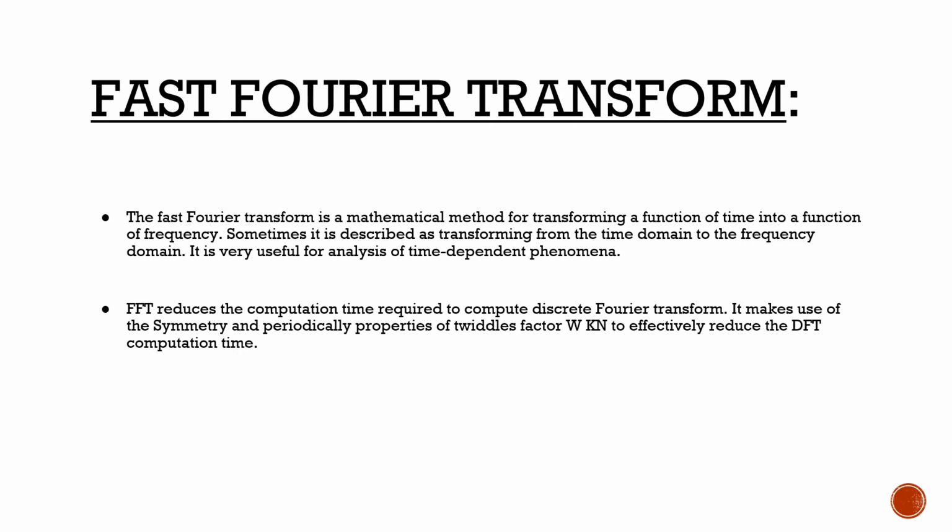This conversion normally takes a lot of time, that is, it is very slow, but using the fast Fourier transform algorithm we can do it faster. This can be done because in fast Fourier transform we factorize the DFT matrix. Fast Fourier transform also reduces the complexity when compared with DFT, and it takes less computational time by using properties such as symmetry and periodicity.